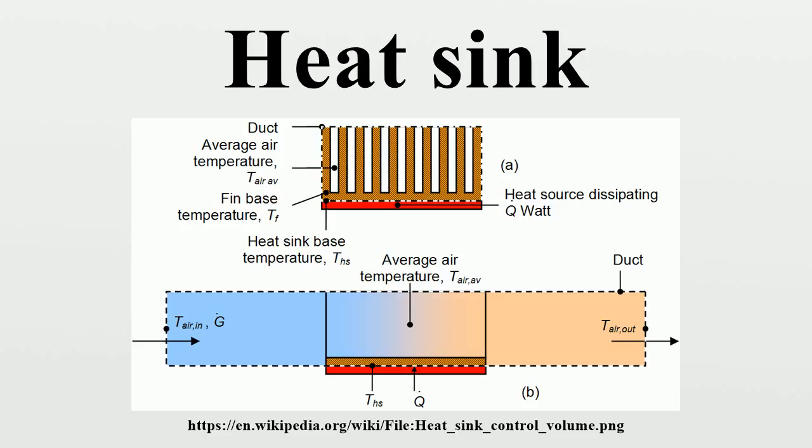Commercial extruded aluminium heatsinks have a thermal resistance ranging from 0.4 degrees Celsius per watt for a large sink meant for TO3 devices, up to as high as 85 degrees Celsius per watt for a clip-on heatsink for a TO92 small plastic case. The popular 2N3055 power transistor in a TO3 case has an internal thermal resistance from junction to case of 1.52 degrees Celsius per watt. The contact between the device case and heatsink may have a thermal resistance of between 0.5 up to 1.7 degrees Celsius per watt, depending on the case size and use of grease or insulating mica washer material.